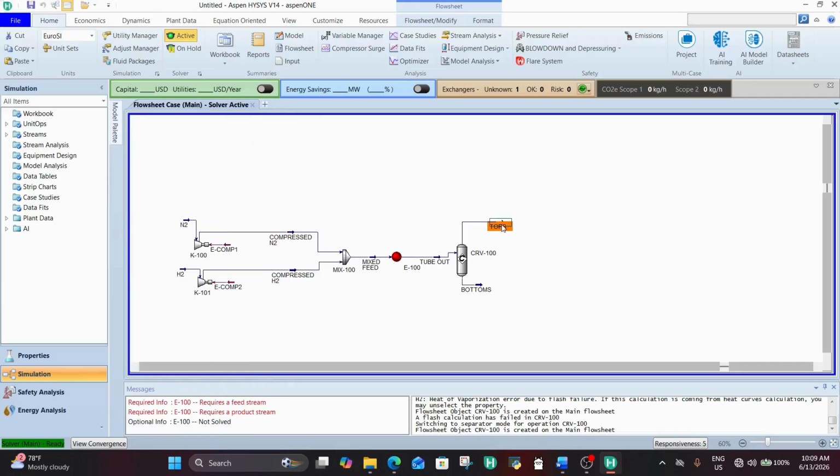Now, showtime for the heat recycling magic that we have been talking about. Take note of our temperature here. It's 633.1 Celsius, our product, and this is 312. So we definitely have heat energy to a very large extent, which we can feed to this particular stream, even though the flow rate is slightly higher, but we still have enough change in temperature to push it higher to a new degree.